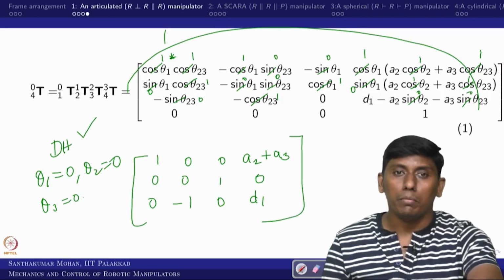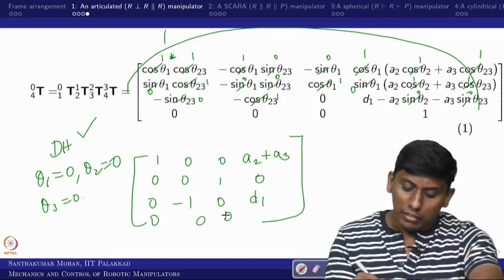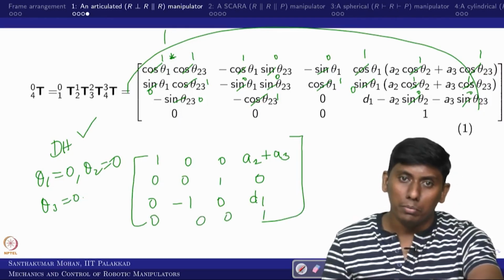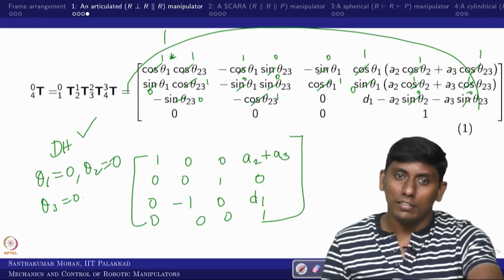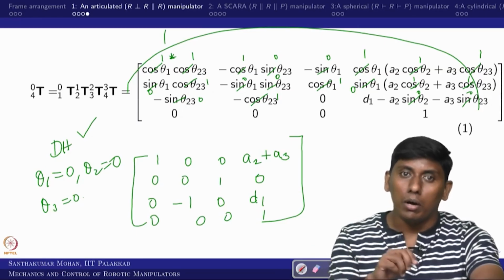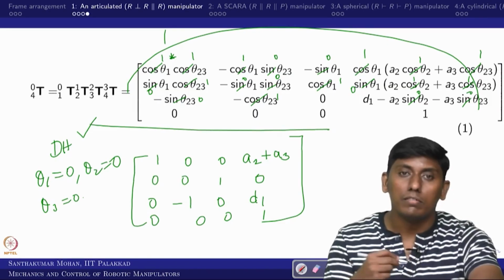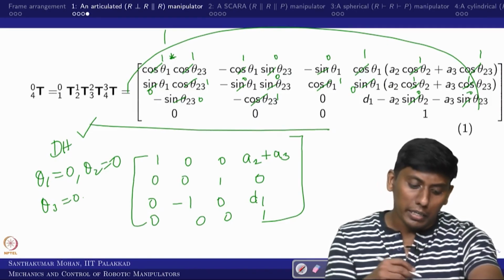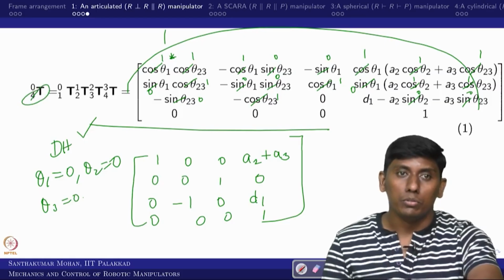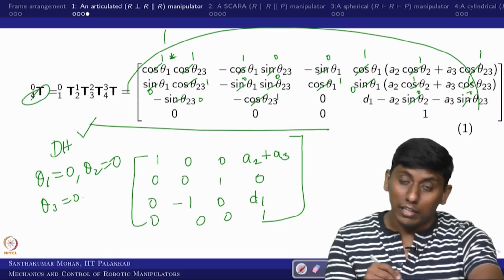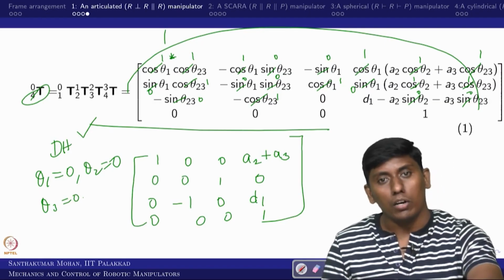So in the sense, what you obtain is the one which you have seen as the home position, that you have cross checked, right? So that is what I said, this is the last task. Once you obtain the DH parameters, you derive the final transformation matrix, in the sense the transformation matrix of 4 with respect to 0, and you substitute your home position and cross verify.